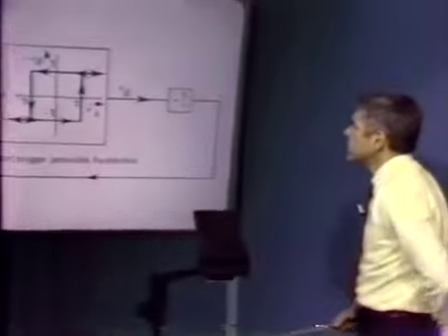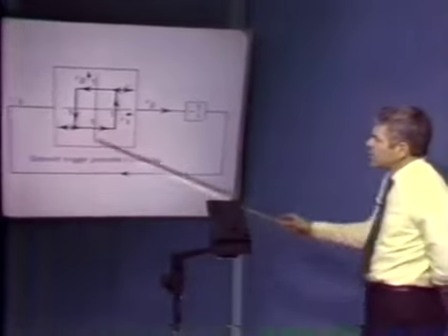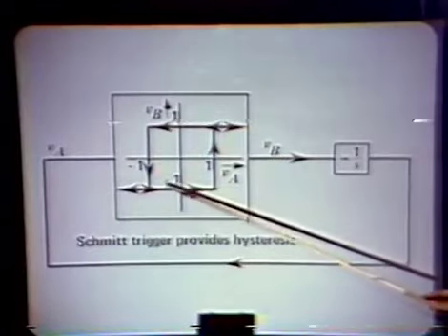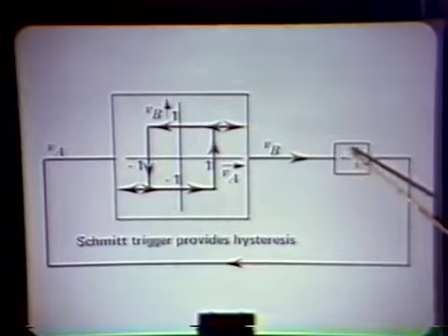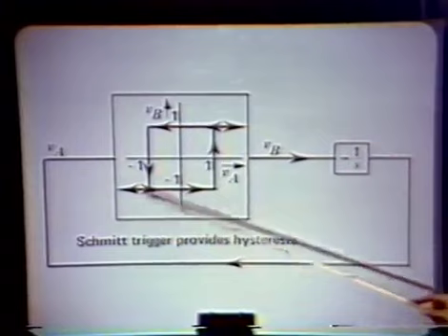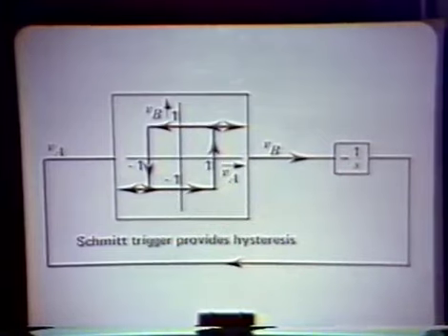There's a fairly popular circuit that's used for function generators, the sorts of equipment that one uses as signal sources in a laboratory very frequently. And that system, or that technique, is shown in the first view graph. What we do is take a Schmidt trigger, here I've shown one that's normalized, and combine it in a negative feedback loop, the inversion indicated here, with an integrator.